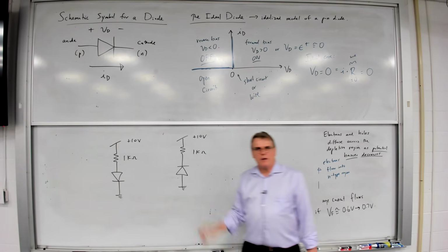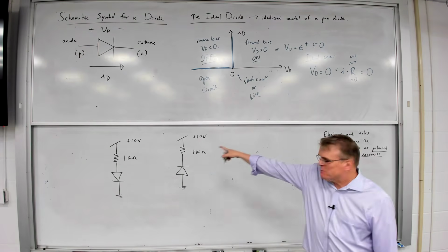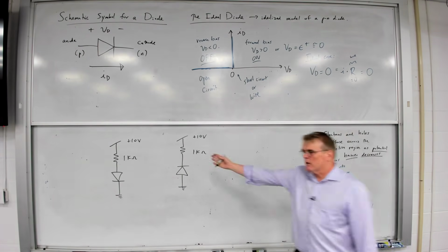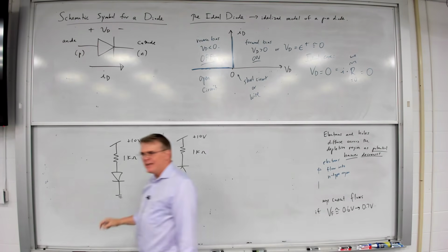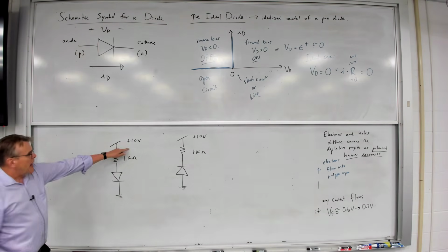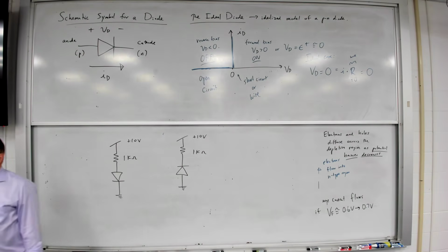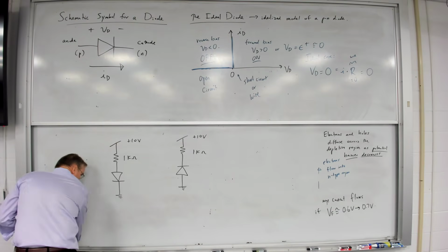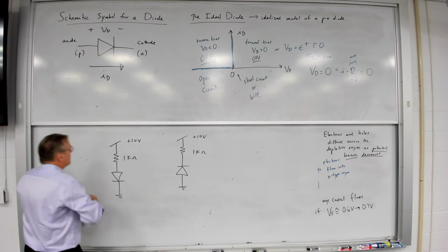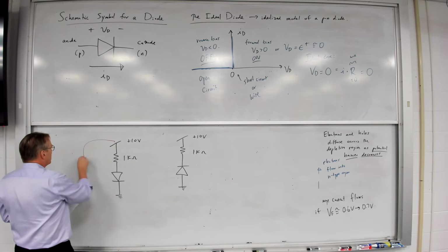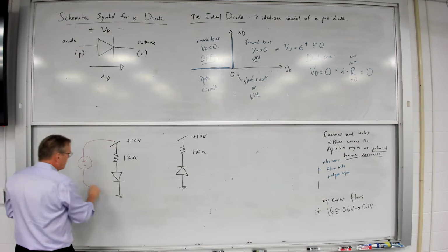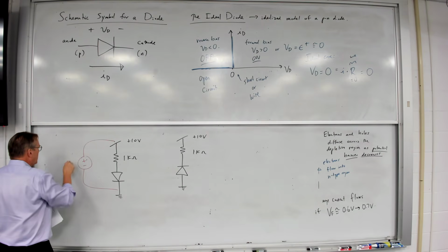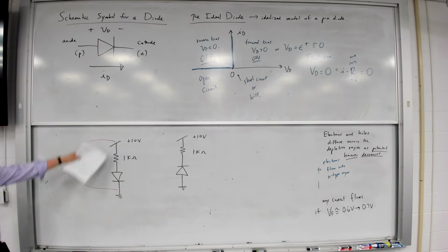Okay, does this look familiar to you guys? The way I'm drawing those power supply terminals? That should be familiar. We did this when we talked about op amps. It is implied that there is a 10-volt source in this circuit that I'm not bothering to draw. As a reminder, there's an underlying assumption that I've got a 10-volt source connected from ground to that terminal.